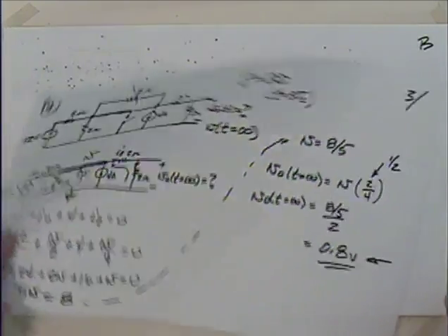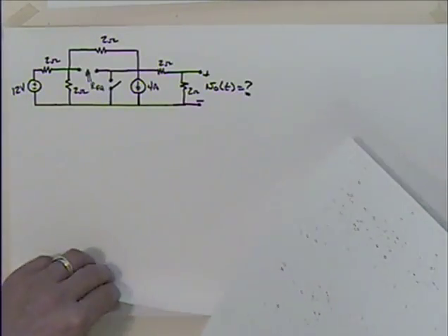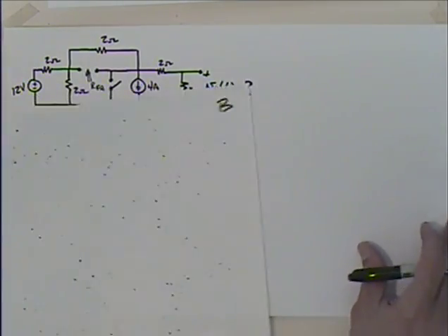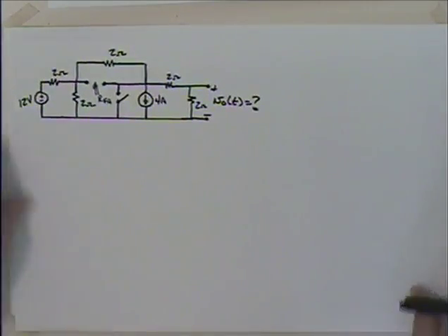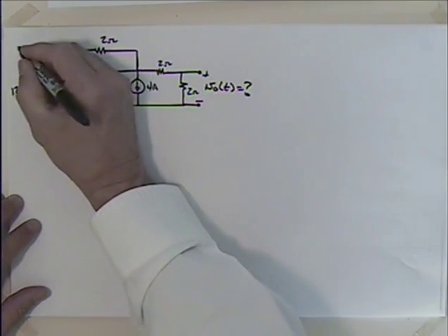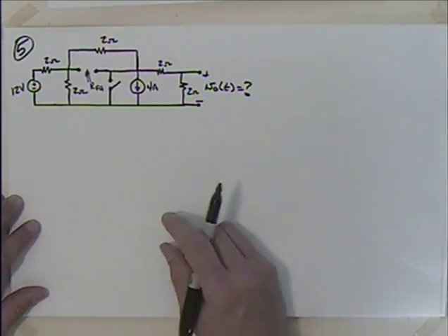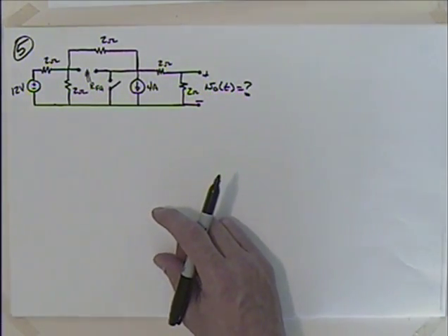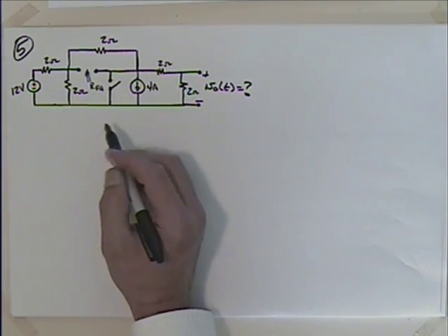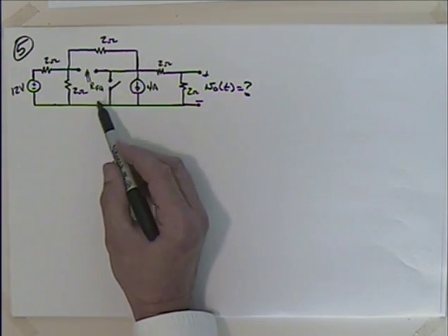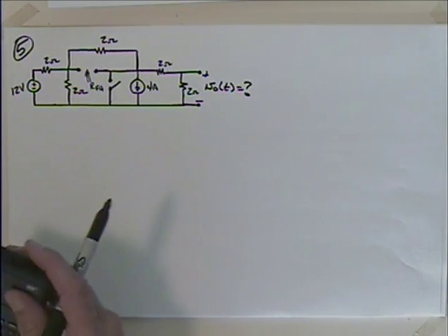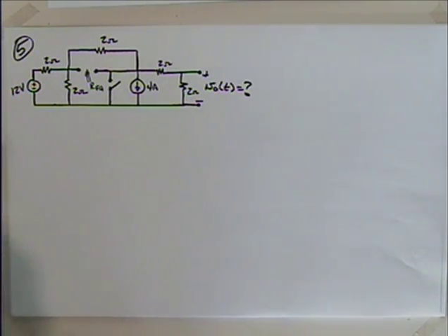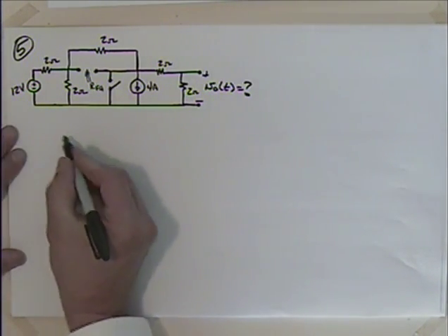Okay, so I've got that. So we're on to step number 5, right? What's 5 about? 5 is about finding the time constant, finding the equivalent or the Thevenin resistance, which oftentimes we get via the equivalent resistance. Can we do that with it? Yeah, we can use the shortcut.